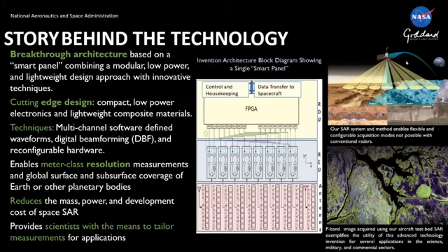These are just pictures of the various types of radars that we have, ranging from the first one, an L-band system that we flew on P3, a DVSAR-2, which shows the first smart panel concept, a diagram of EcoSAR, which is a dual antenna P-band system, so it can do interferometry in real time, and it also is extremely versatile in how it acquires data, and we'll show more about that as we go.